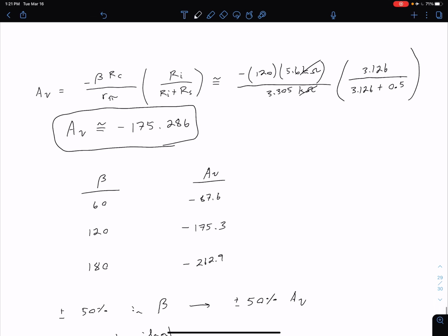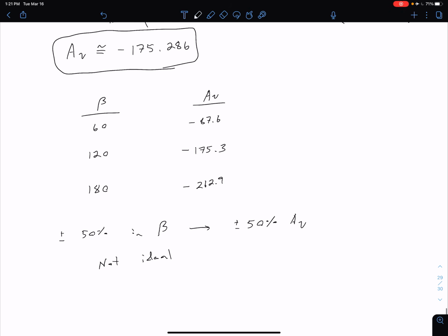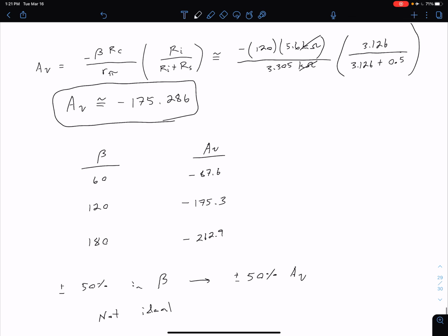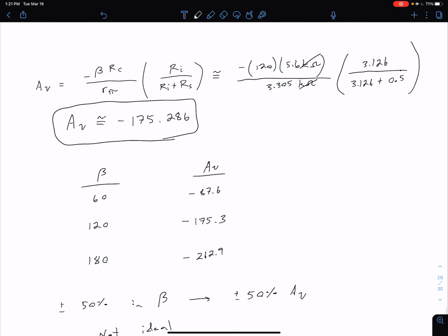So going back to adding the emitter resistor, which we're going to do in the next video, it's going to decrease our gain, yes, but we're going to see a lot less variation as our beta is changing. One other thing to note too is that, of course, as we're changing this beta value, any change in our beta is also going to result in a change in our Q point, so a change in our ICQ, and consequently a change in our small signal transconductance g sub m.